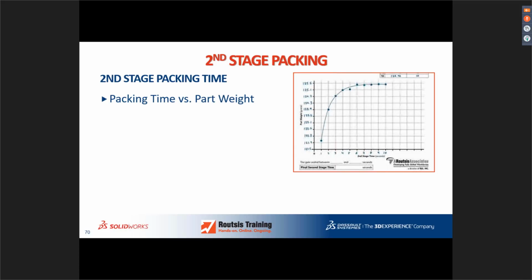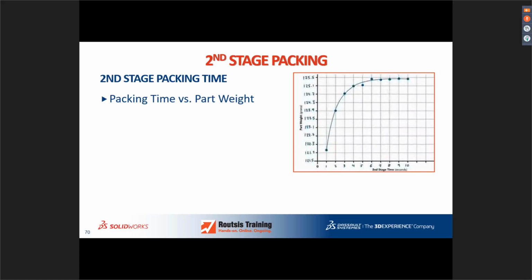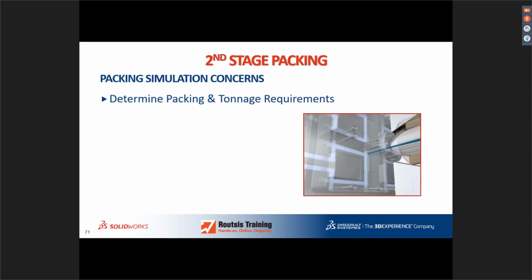And what's important is this: we'd like to determine packing time versus packing weight. If you look at the right-hand side of that curve, you'll notice how things level out. We want to see that point. You can see between 5 and 6 seconds where we've got this transition. That's where we go from material flowing into the gate to flowing out of the gate. Simulation also helps us with determining packing time and the tonnage requirements so we don't flash the part.